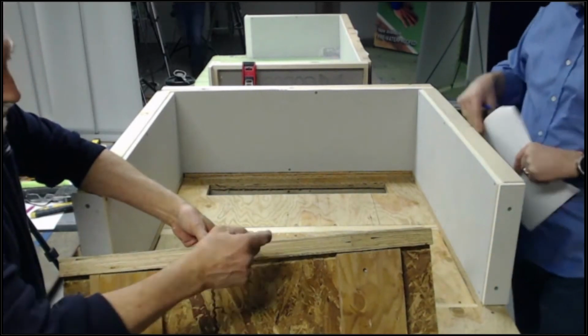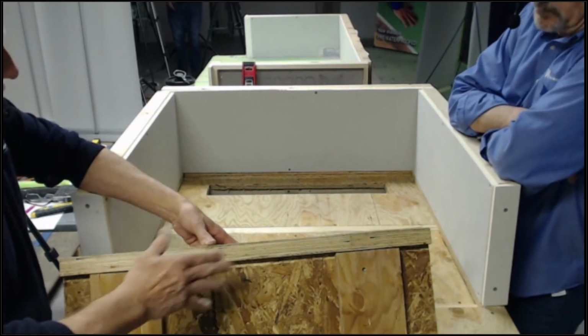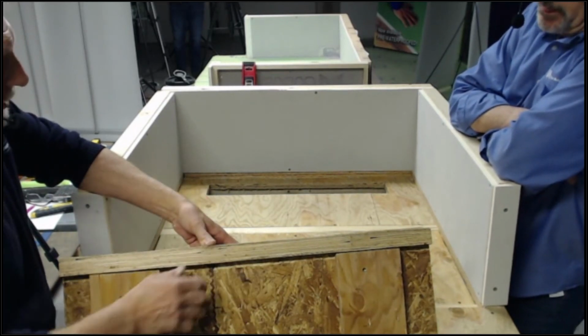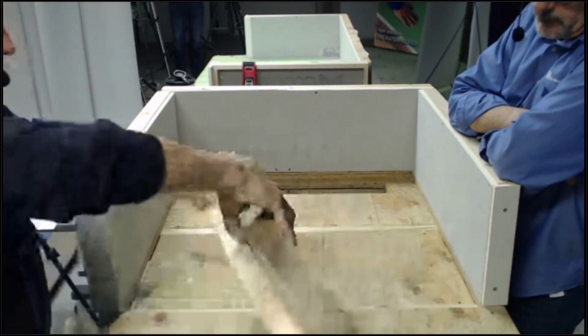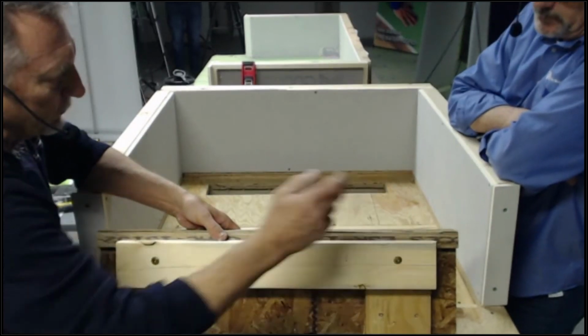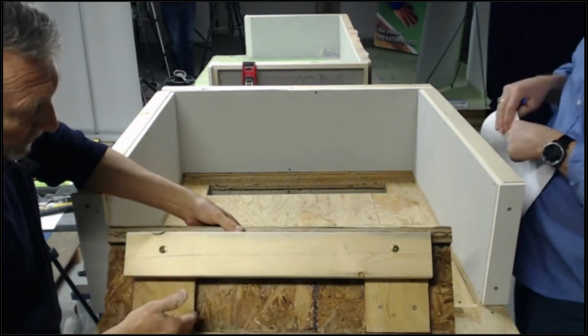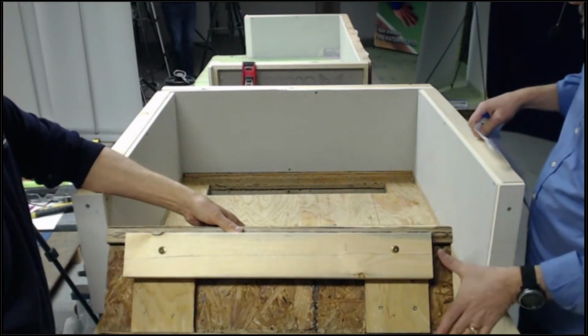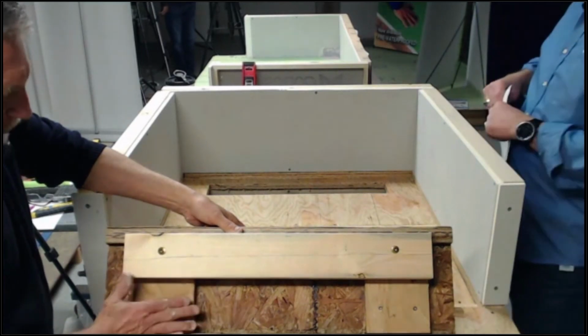You can't just toenail into the web. You don't want to screw into those I-joists with a structural screw. You start splitting that, now you've got issues. There really isn't enough area to do that. So as you see, I got blocking sandwiched in, and I did it on the other side too. Then I used my structural screws and put my blocking onto my webs. You've really simply filled out the gap between the two, typically with 3/4 inch